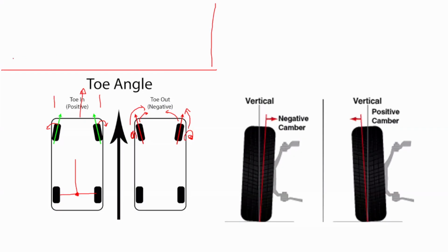So what happens if you drive with a standard air pressure in a sand condition or desert or beach? Normally with the standard tire pressure, the tire's contact area is reduced, right? So there is a high possibility of having some stuck wheels inside the sand, right?